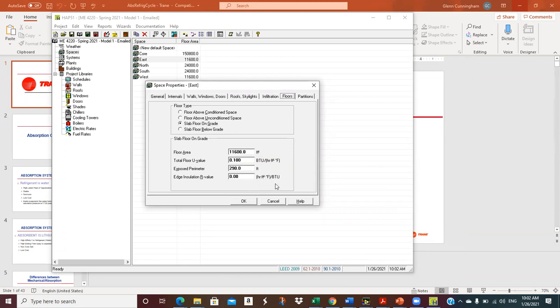And up north, they actually put insulation on the outside of the slab to reduce the heat loss. It probably doesn't do much in the summertime, but in the wintertime, when you have cold enough temperatures, it also keeps the cold from penetrating up under the building through the slab, which can get cold enough to cause condensation on floors.